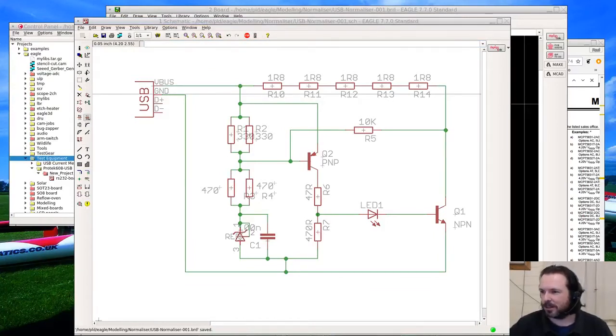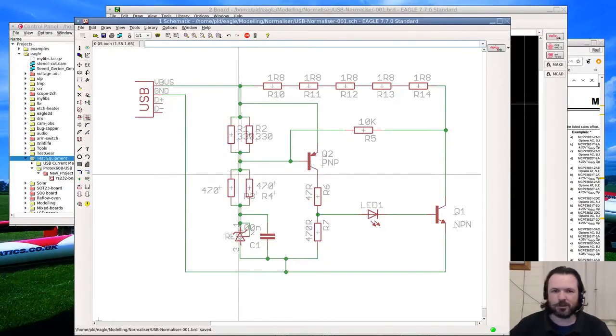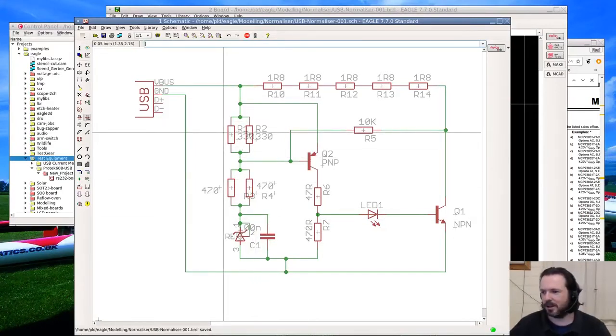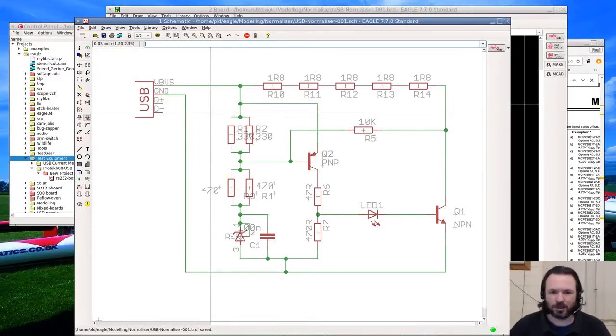Leslie, at what point would it turn off? Depending on the resistor values, it turns off at around about 3.7 volts at the moment. That's the whole point of all these trimming bits. It's entirely up to what you choose to have.